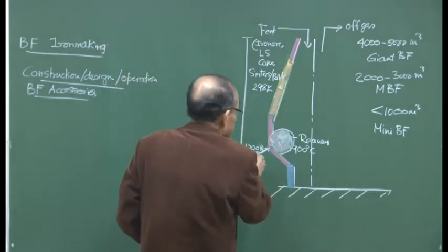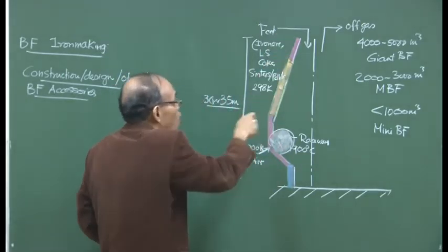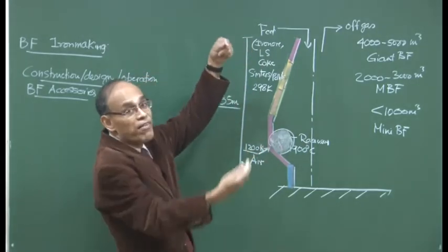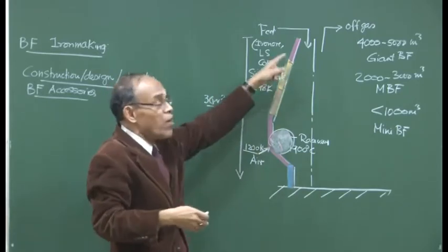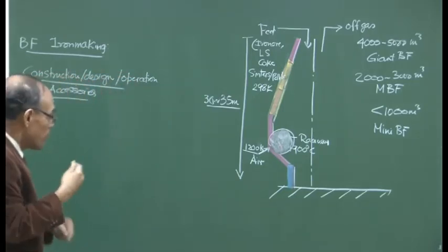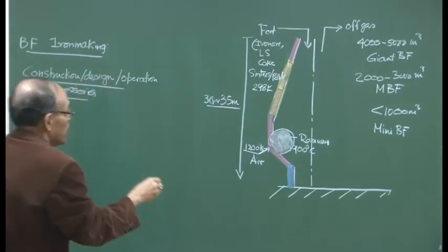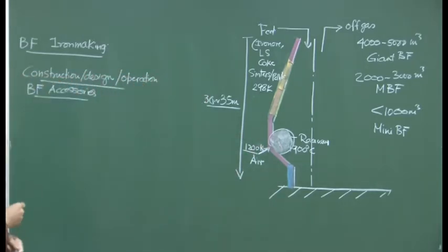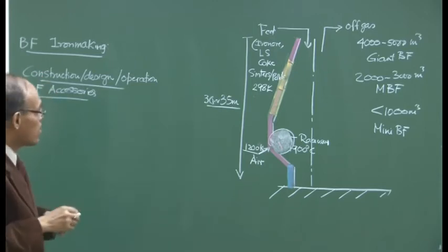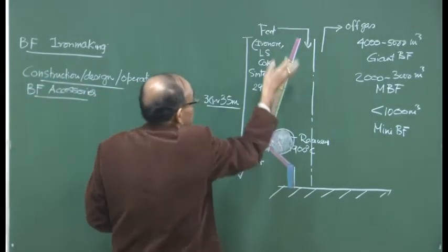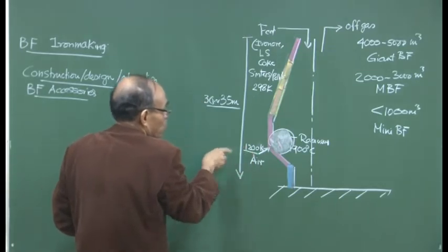Therefore, we can say that the descending column of iron bearing material and the ascending column of gas travel within the furnace in opposite directions, and that is why the reactor works on the counter current principle. The descending column of iron bearing material and the ascending column of reducing gas, which is carbon monoxide, meet, and as a result an exchange of raw materials or ingredients takes place. Because the temperature decreases from 1900 degrees, the stability of carbon monoxide will increase.